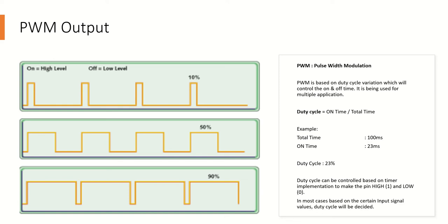Different controllers will support multiple timers, timer 1, 2, and timer 1, 2, 3. It could be multiple timers, up to 10 timers is also possible. In the latest ones we have many controllers like that. So you need to have a timer configuration, and you need to configure the timer with respect to the on time and off time. And if you want an interrupt for your timer, you can also configure that.